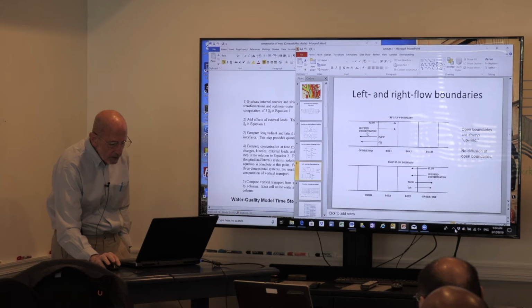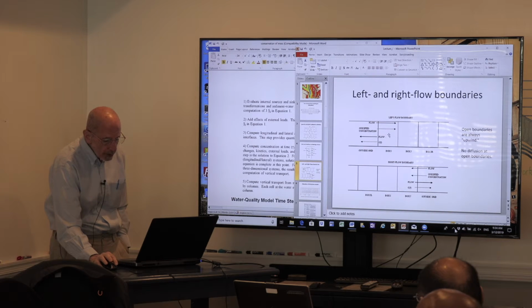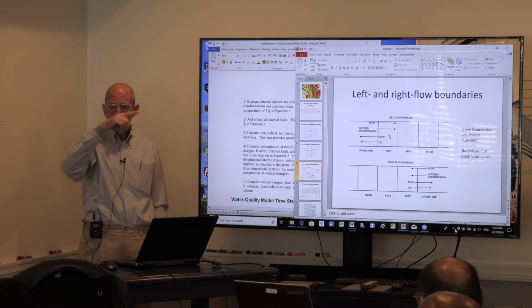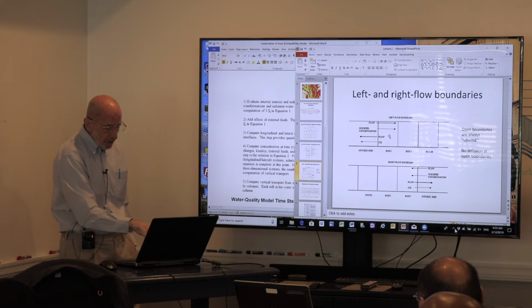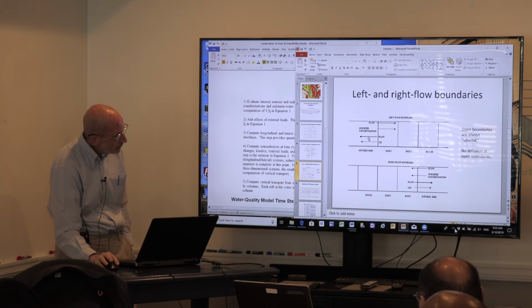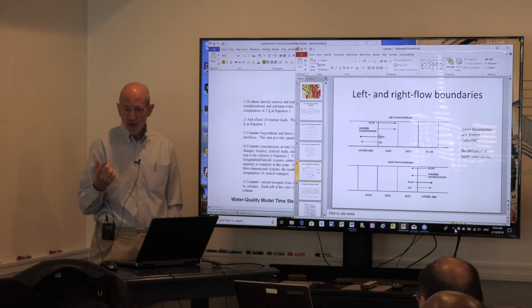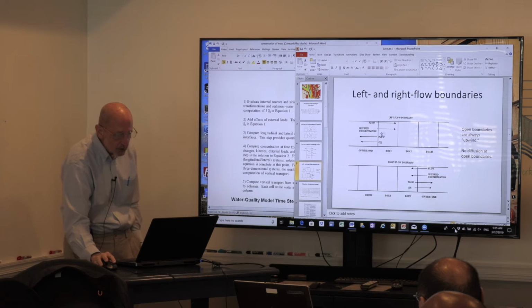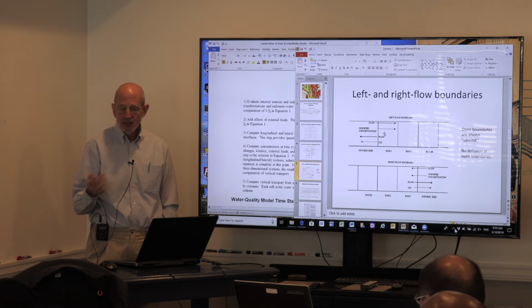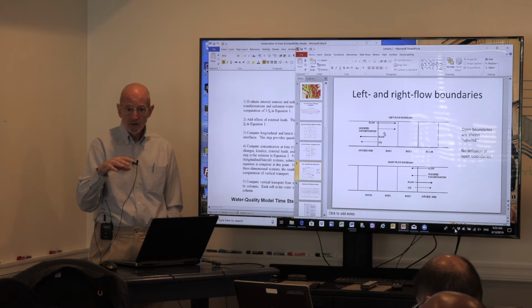And we do that for a reason. Number one, we don't have two cells up, but also, if we used QUICKEST, the concentration in this box would be one of the three points to which we would fit our parabola. So the flow across this face would not actually be the specified boundary condition. It would be, if you will, that the concentration in the box downstream would be taken into account when we computed what flows across that face.